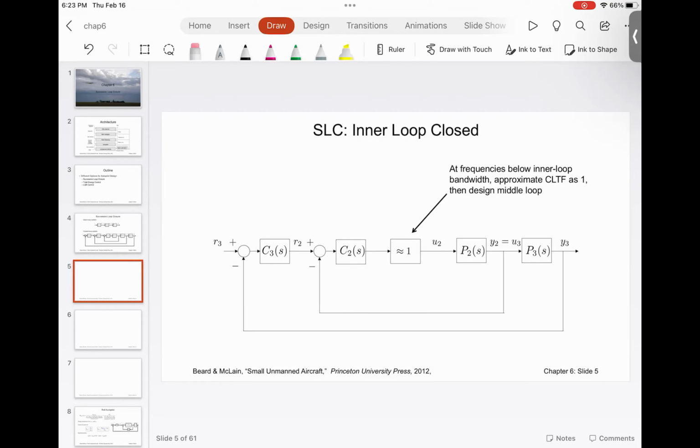So exactly the same thing, which means when we try to close the inner loop, we tune the gains and the system parameters in such a way that the inner loop becomes one. That is the principle. How do we make it happen? Once again, whenever a pilot is flying an aircraft, you have this control system, something like a power steering mechanism, that is amplifying the pilot stick input to move those heavy control surfaces.